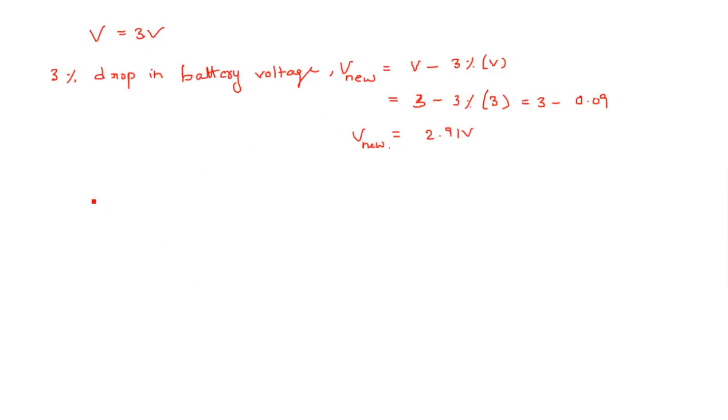Okay, now R2 is equal to, why is he asking R2? Because R2 is the resistor connected across the meter in series type ohmmeter. R2 is the potentiometer which is connected across the meter to adjust the 0 ohms. R2 is known as zero adjustable resistor. Remember, R2 is known as zero adjustable resistor because its value is adjusted to get zero deflection.